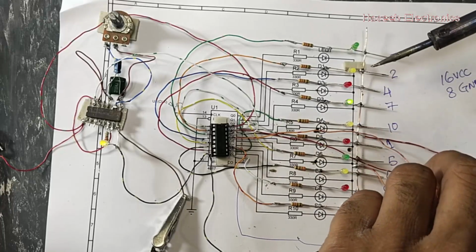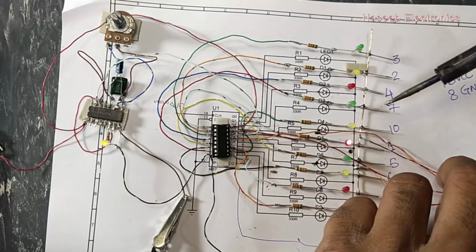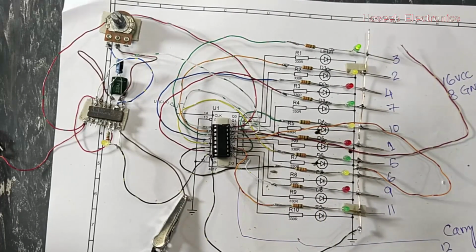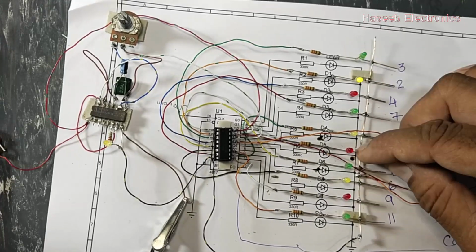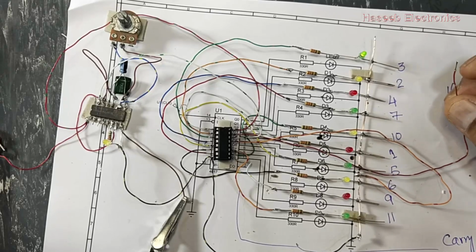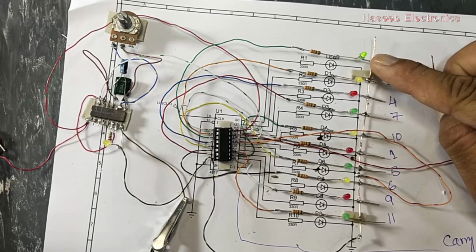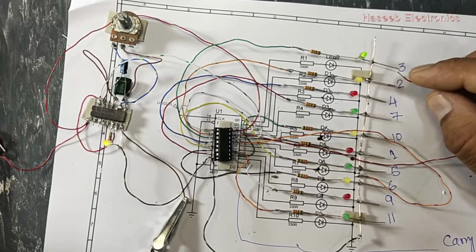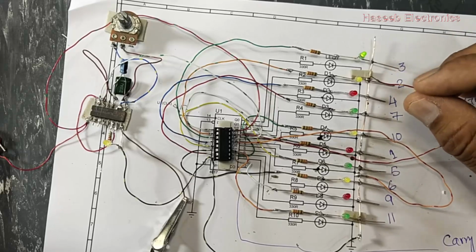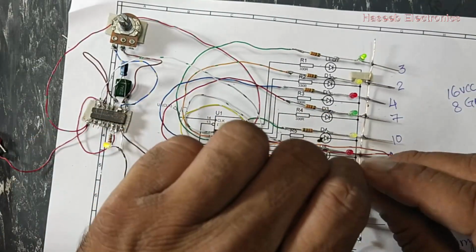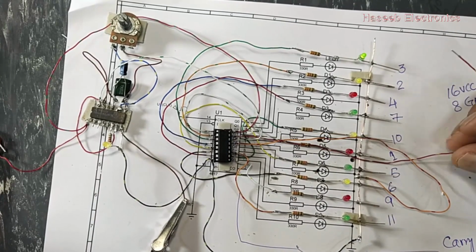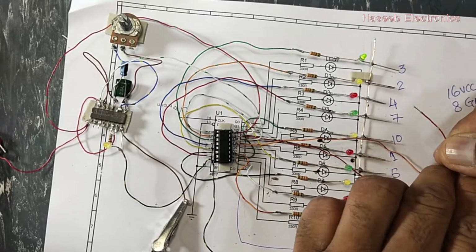And then we have pin number 15. That is master reset. I removed this pin from ground. This IC is stopped now. Master reset, I removed master reset, pin high. Now it went to pin number 1 and stopped. Anytime we want to reset this IC, we will connect this pin to positive. So it will go to reset mode. So it is its reset. Now it will start from 0.